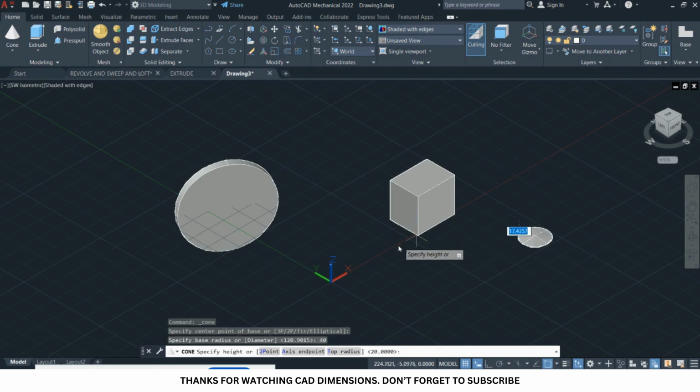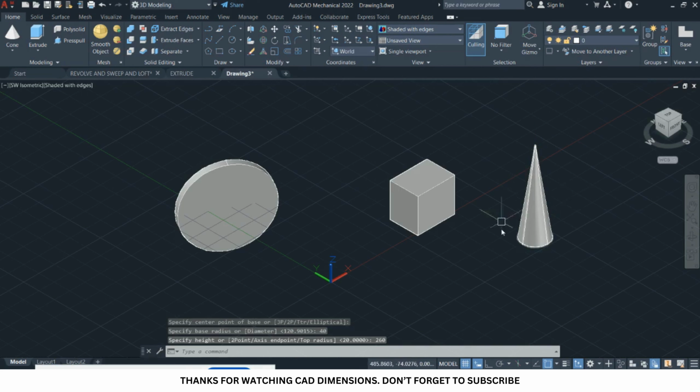All right. So there are other options you can see on the command line. We have the axis endpoint and all of that. And the axis endpoint helps you to actually change the direction or the endpoint of the solid primitive that you've already modeled. Okay, so maybe for this one the height will be 260, and that is what you have over there.